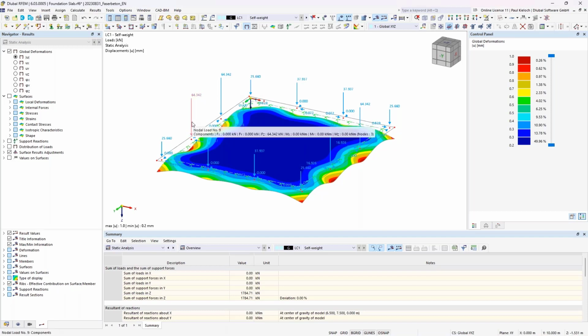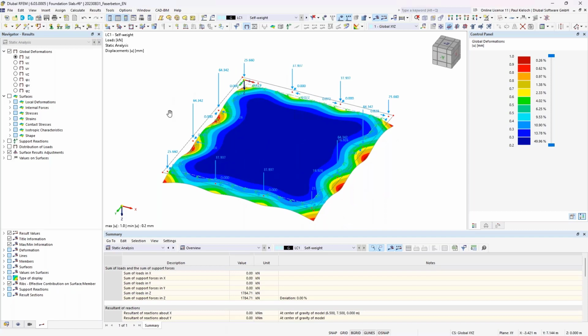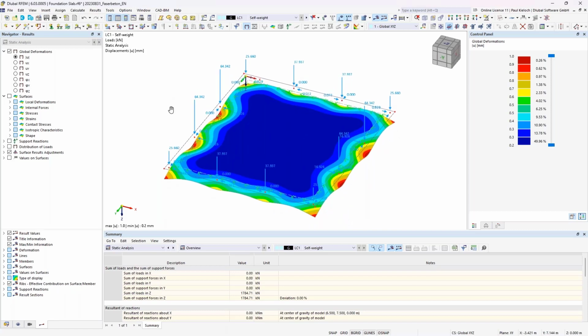Now it's an object load, so a nodal load, and it's always in context to a certain node, so that we can also use it for the punching. And both files are now connected together regarding the update process. So that is new in RFEM 6. Basically, that was everything regarding the modeling of the structure and the load.